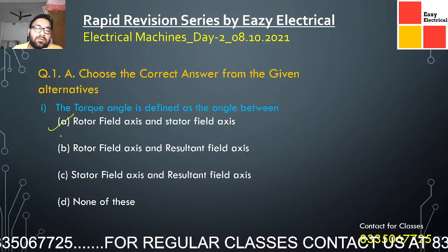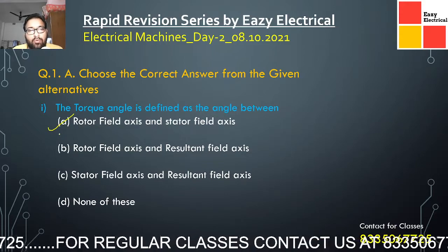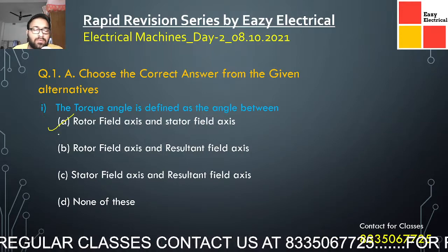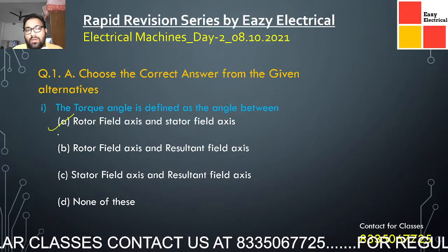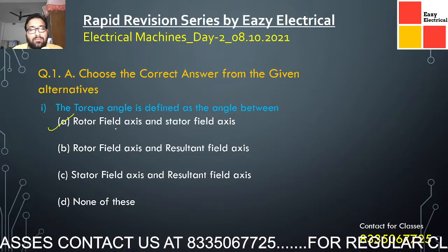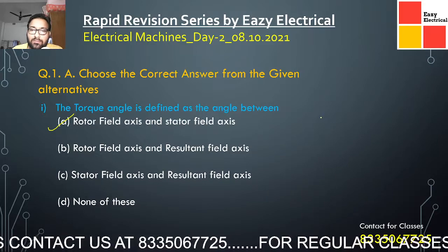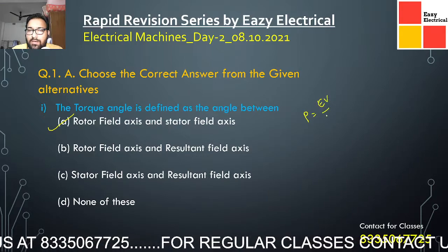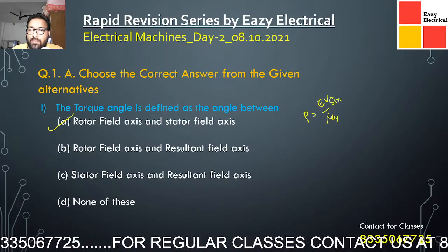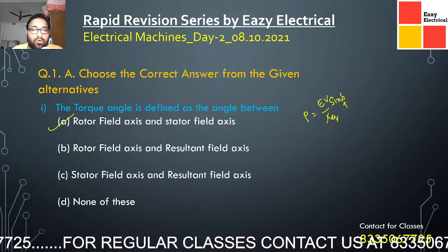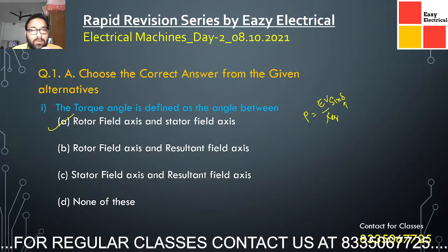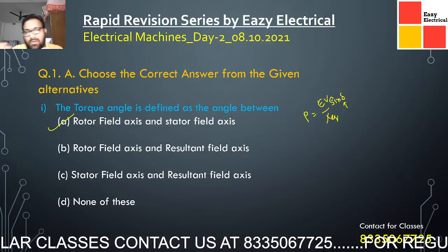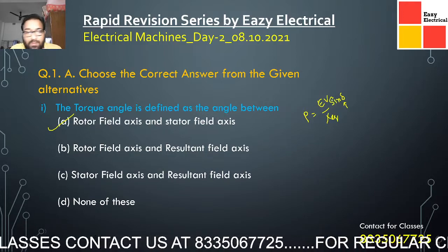Okay, so in details in power systems, when we deal with the torque angle, there are certain equations where you will be using this torque angle term. Suppose there is a power expression, E V divided by X eq into sine delta. Now this delta term is basically your torque angle. This is the power delivered from one state to another state for a synchronous machine. This equation I'll deal with you in the power system class as well.